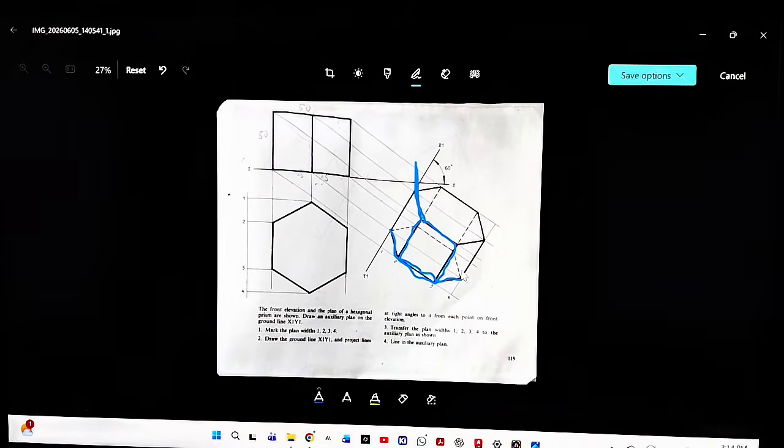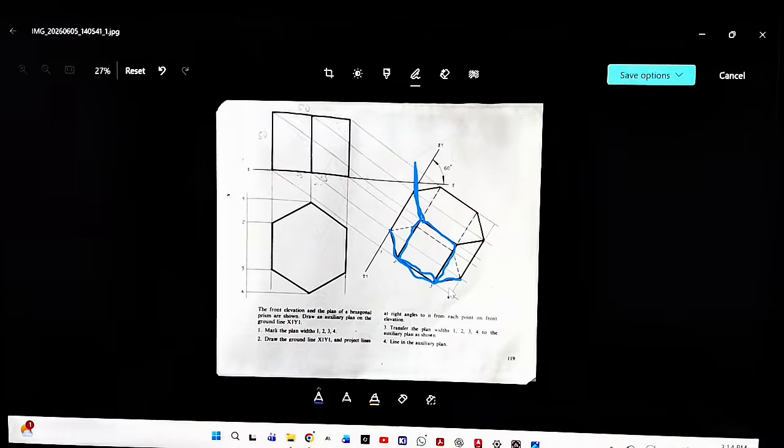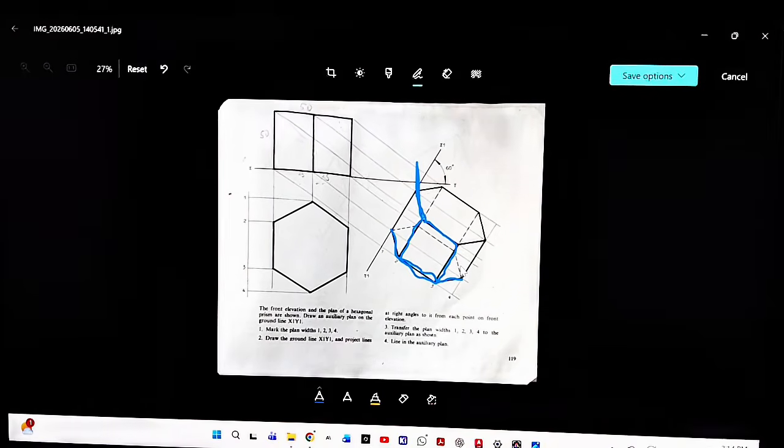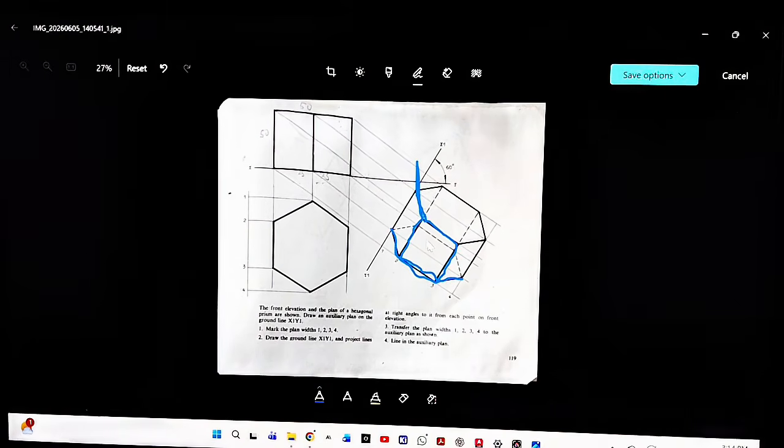If you turn it around, as you see this 1, 2, 3, you'll see this 1, 2, 3 as well. But because you've not turned it around, you can't see it. You have to imagine that you can see all of them at once. So these parts that you can't see, but you know they are there, will be dotted. And this place is a vertical line. Don't mistake it for a horizontal line. It's a vertical line.